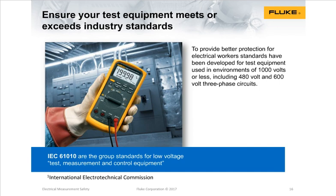So we're shifting gears here. That was NFPA 70E. Now we're going to talk a little bit about the International Electrotechnical Commission, IEC for short. And there's a standard called IEC 61010. And these are the group standards for low voltage test, measurement, and control equipment. When we say low voltage, it's 1,000 volts or less. And these are standards that are developed primarily for manufacturers that deal with what's called creepage and clearance inside the instrument. And it's based on the amount of energy that can take place from a type of arcing incident.